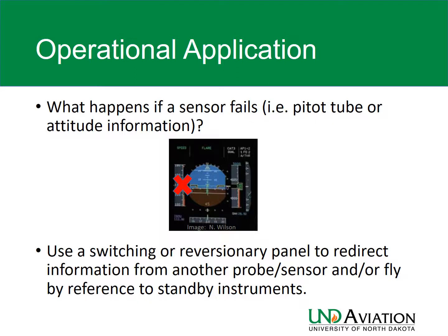So that would be a fairly minor issue, losing one air data source on pitot source if you have two others. Yeah, it's important, but if you've got two others that are working fine, this flight should be able to be completed without any incident. And then of course you're going to contact maintenance through ACARS or other available means and then have it addressed on the ground. So there should be a way to remediate this with fairly low impact to the crew. If you have more than one failure of a redundant system, then it gets a lot more complicated, obviously.